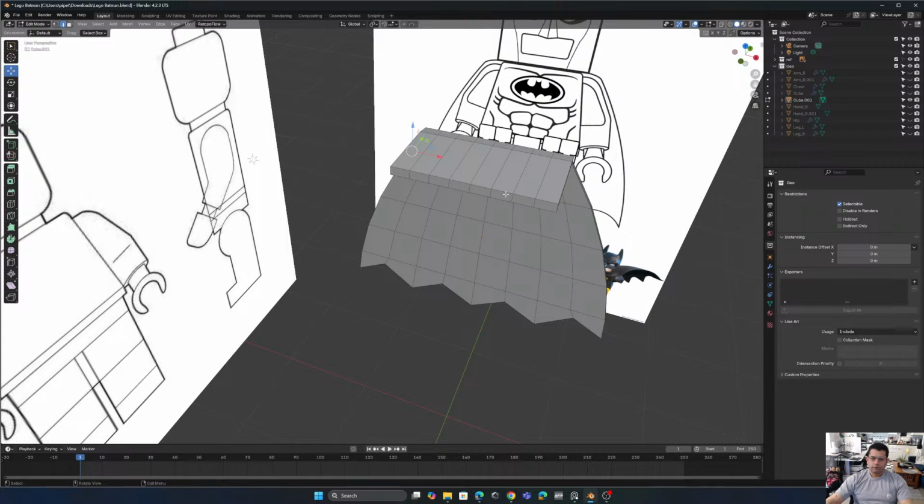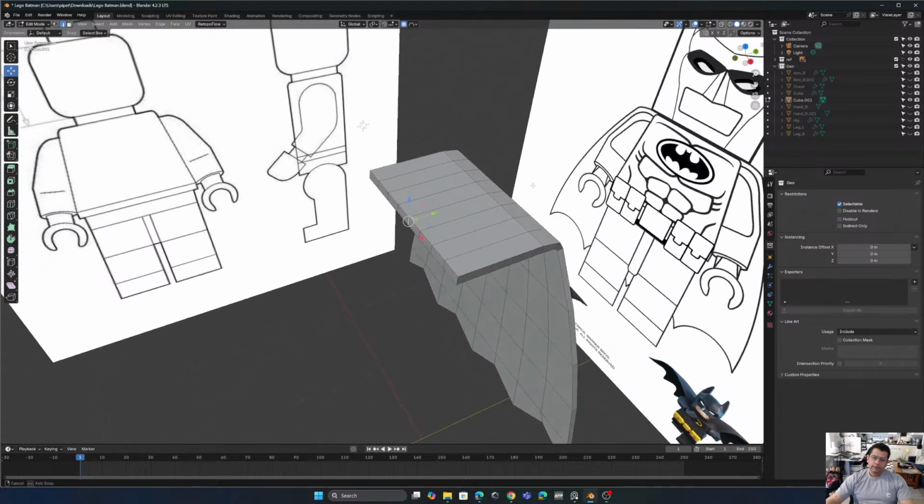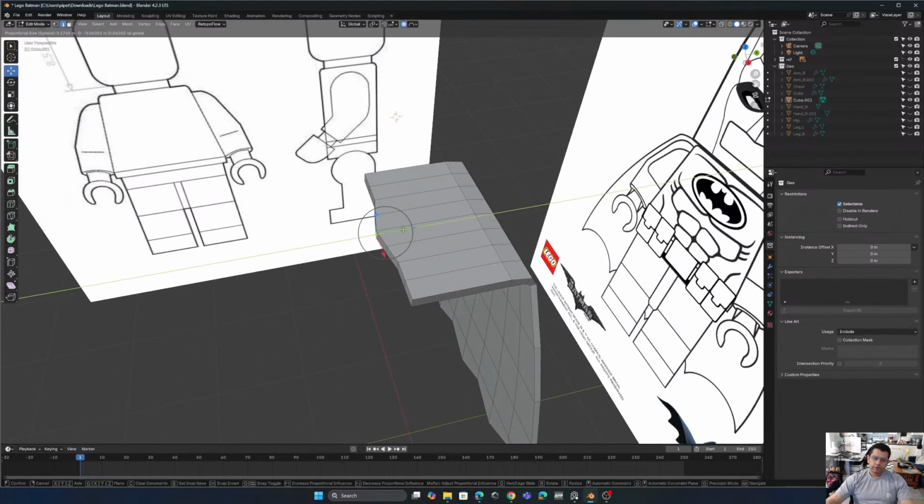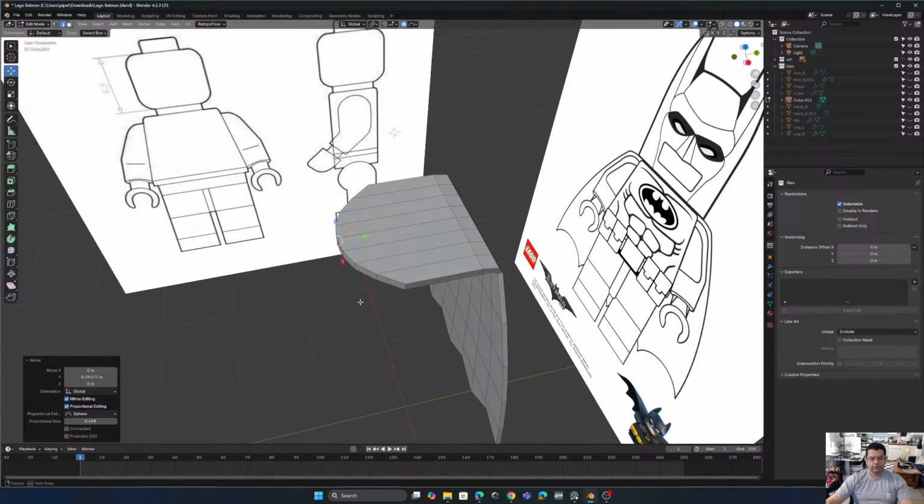Okay. We have 8 faces over here, so we're going to select this edge, activate this option, or pressing O to get the proportional editing mode. O, or clicking here. We're going to select the arrow, and with the scroll, increase the affected area to create a more curved shape over here. Okay, I liked something like that.